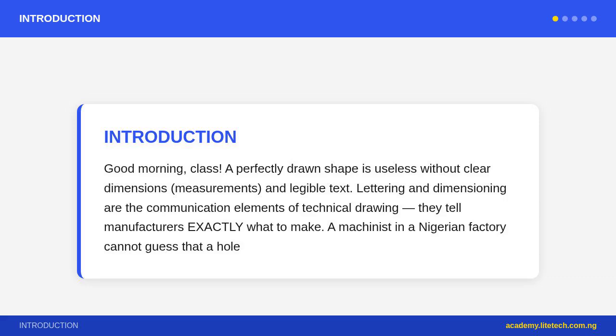Technical lettering standards. Lettering types. 1. Uppercase, capital letters, preferred for all main text in technical drawing. 2. Lowercase, used for some annotations and notes, less common. 3. Single-stroke Gothic lettering, the standard form for manual technical drawings. 4. Vertical or inclined, italic at about 75 degrees, both acceptable but must be consistent throughout one drawing.